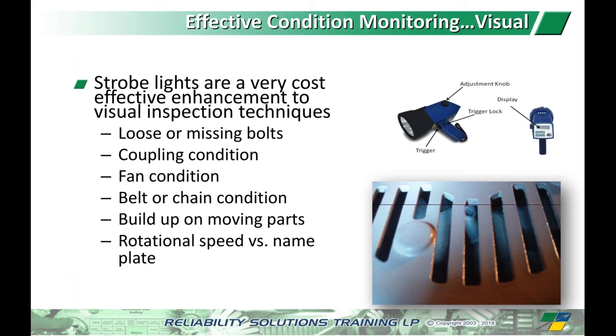Flow makes it go. So with a positive displacement pump, the amount of flow you get is directly related to the rotational speed of the pump. So taking a tach or a strobe to measure the speed of the motor, measure how fast the pump is turning, and validating that it's within specifications is a very important step in troubleshooting fluid power systems. One of the first things I'm going to do is ask: what speed is it turning at? Is it at the right speed?